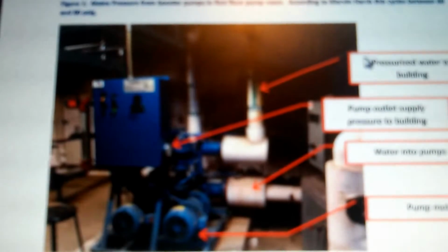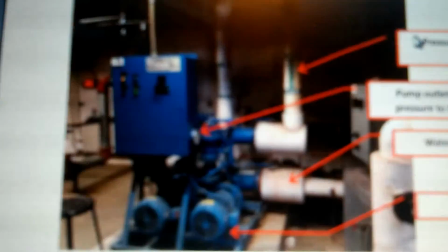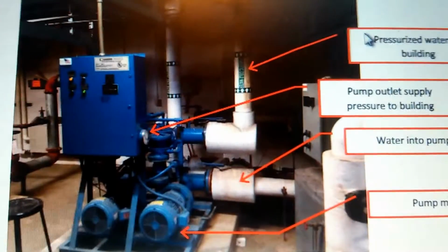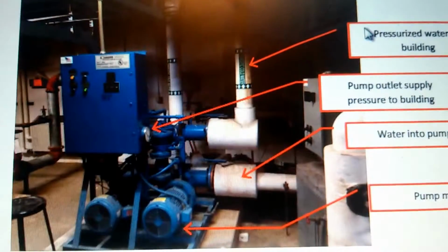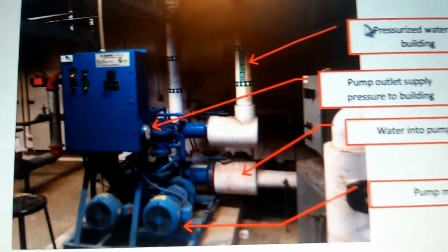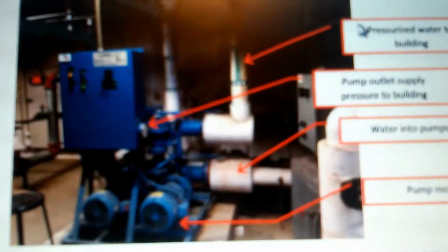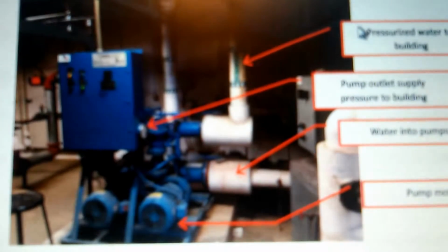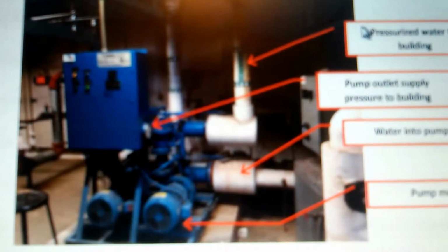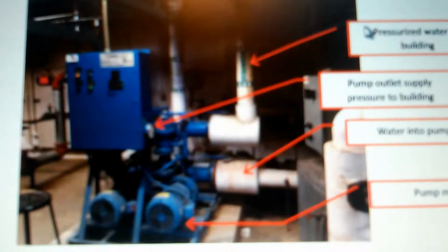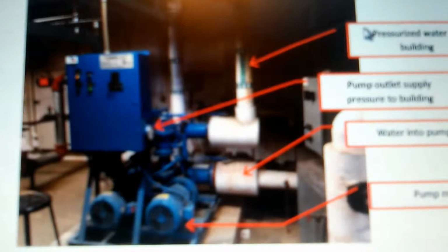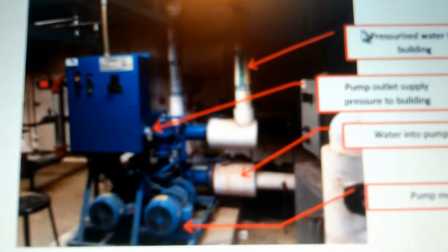Now, it keeps a constant 70 psi pressure, taken from this picture of its gauge. It is always supposed to be at 70 psi. Not supposed to be higher though, but you should check it just to see if there's an anomaly or there's a problem. And also, there's a high chance of you not being able to get access to this room, as very few people have a key to it, and it's almost random when it's unlocked or locked.